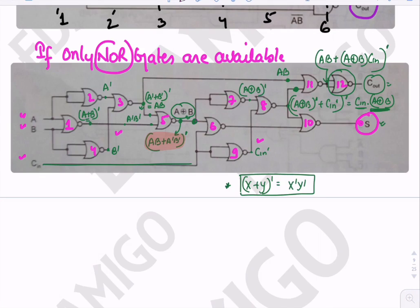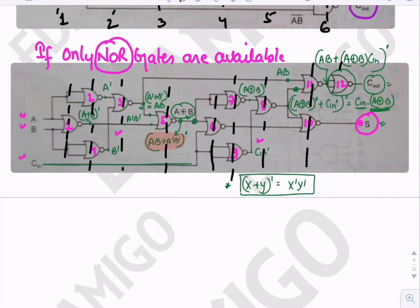Here we need 12 NOR gates to design the full adder. Okay. Now if we look at the levels, so this is level 1, this is level 2, this is level 3, this is level 4, 5, 6, 7, 8, 9. So 9 levels. So we have 9 NOR gate delays.